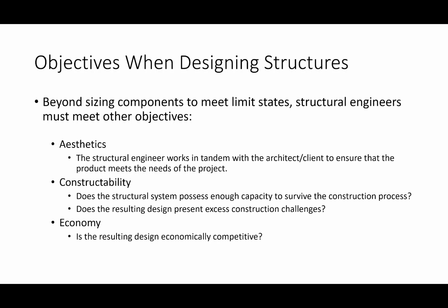On top of that, you do need to develop a system that is easy to construct and erect. There are plenty of memes out there of connections that have been designed by engineers that are pretty much impossible to put together in the field. So you want to make sure that the details you're putting forth actually make sense from a fabrication and erection standpoint.